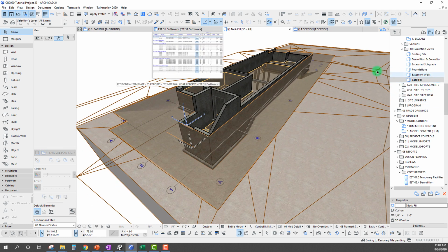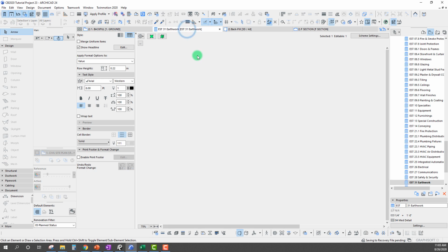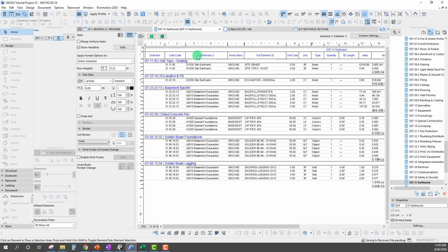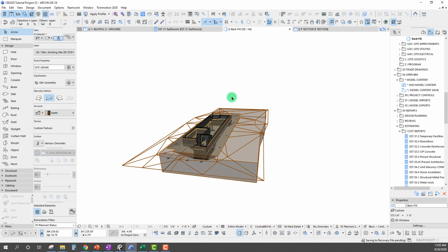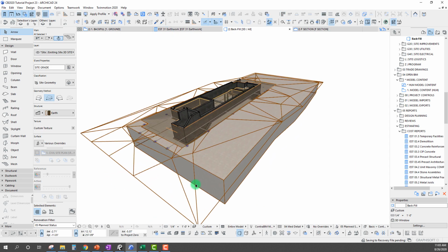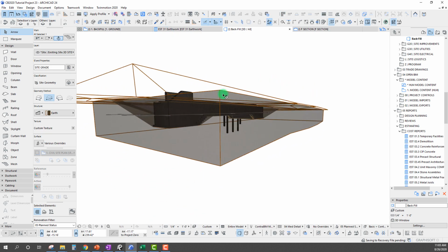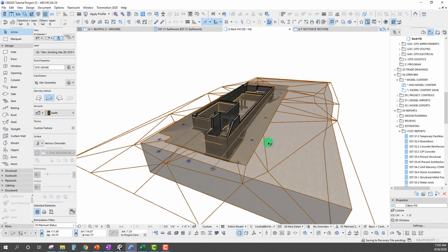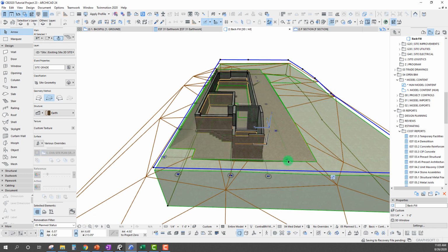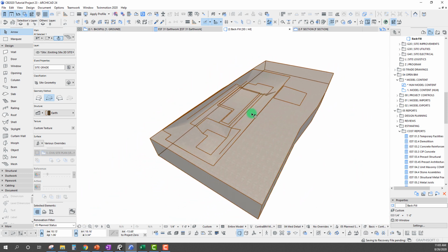So let's go ahead and fire up this earthwork report, and let's just see what we get. We can see we have a few items here. We have a site grade. Now with this, let's just highlight in 3D. You can see that that is kind of our main mesh here that is really acting as our site topo as well as our excavated mesh down below there.